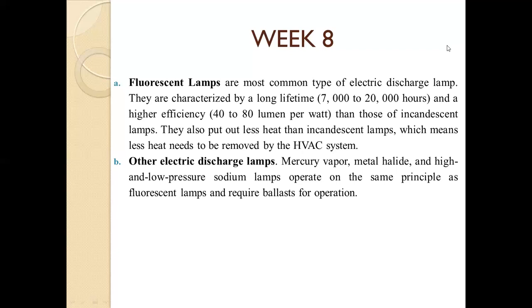Each type of HID lamp has possible uses within the hospitality industry. While incandescent and fluorescent lamps light almost immediately upon being energized, the strike time, or the time required for a lamp to reach full output from a cold start, for HID lamps can be several minutes. In addition, the time required for a hot HID lamp to restrike is usually longer than the strike time. These longer strike and restrike times can be a problem in certain applications, such as locations that need emergency lighting.